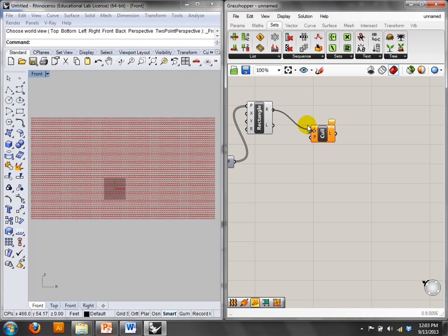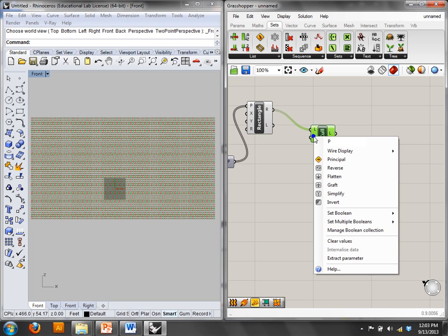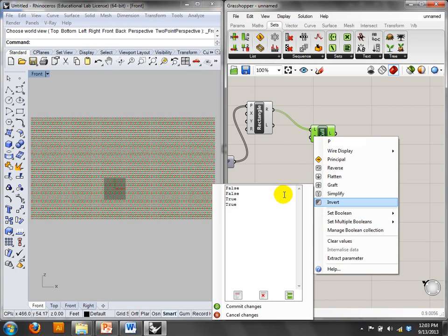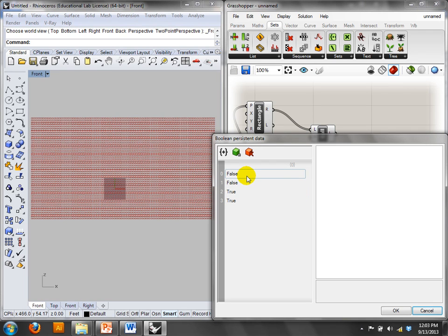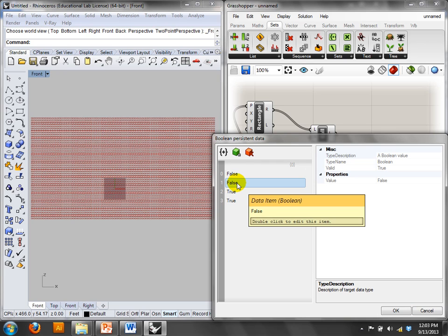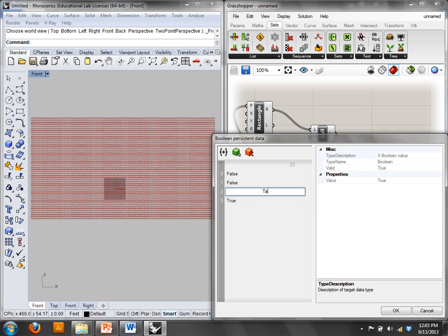So I could take something here, and cull pattern is really great because you can go in and instead of having an nth or random, you can actually say, okay, remove 2 and then keep 2, right? Or you can say remove 3 and keep 2. You can do any kind of pattern you want if you can spell it correctly.